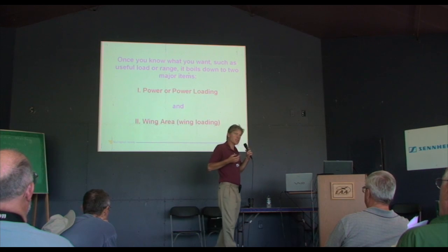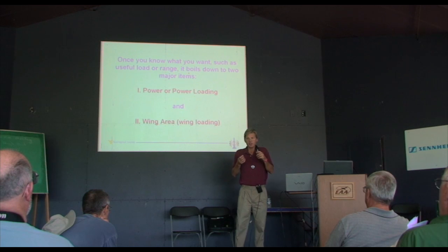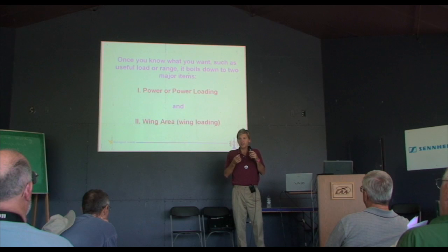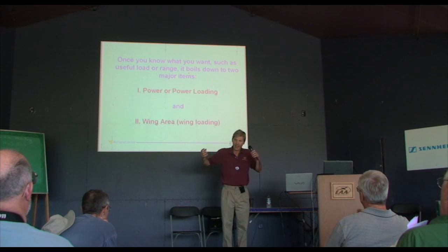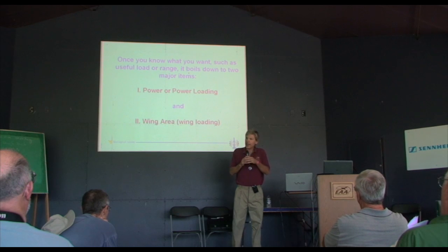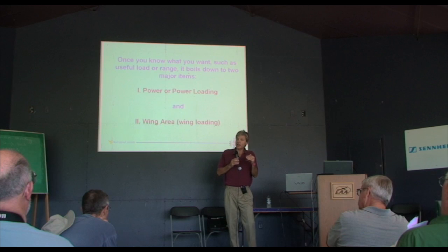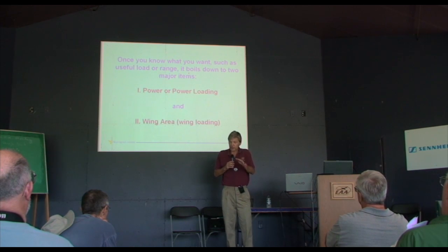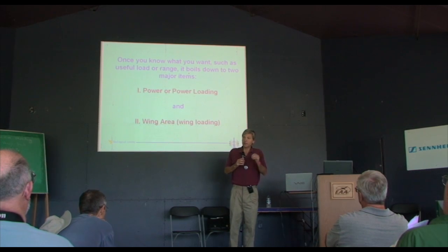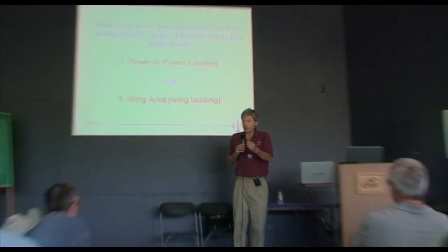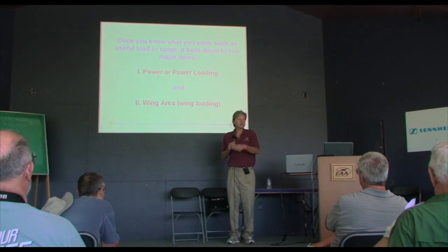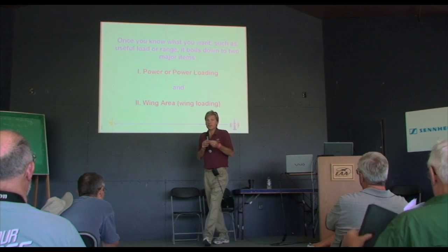And you're probably wondering what I'm saying. What I'm trying to say is, when you add a pound to the aircraft, you actually end up adding 4 or 5 pounds by the time you take everything into account. If you want to add a pound of useful load and maintain the same range, performance, rate of climb, and everything else, by the time you're all said and done, you end up adding about 5 pounds. Because it takes a little more power, a little more fuel, a little more structure, a little more this, a little more that.